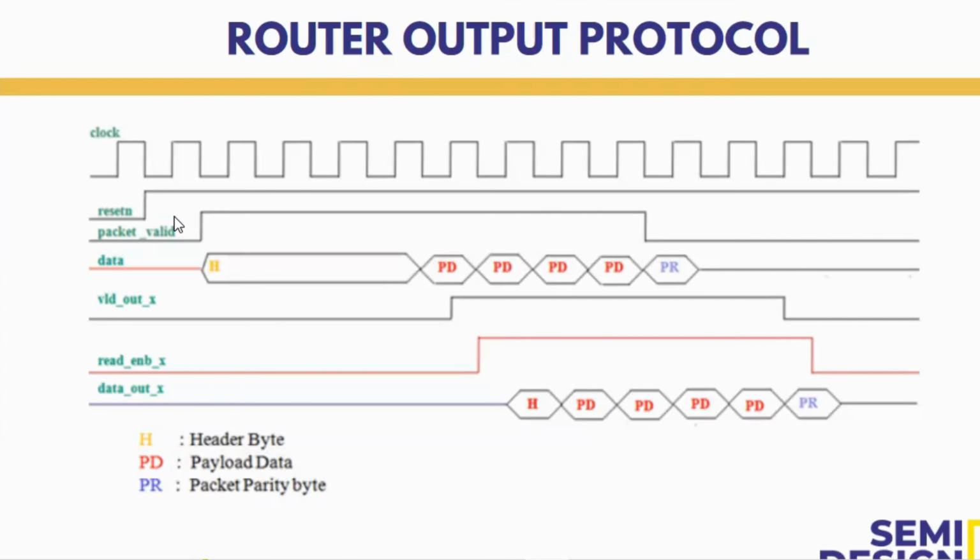I think you would have known about setup time and hold time, right? So for that purpose, they have chosen the falling edge. But you can also use the rising edge in case you are using some synchronization mechanisms, like in SystemVerilog and UVM, where we have clocking blocks to provide synchronization. In that case, the data will be stable even if you try the rising edge. So it is as per your wish; you can choose the rising edge or falling edge.